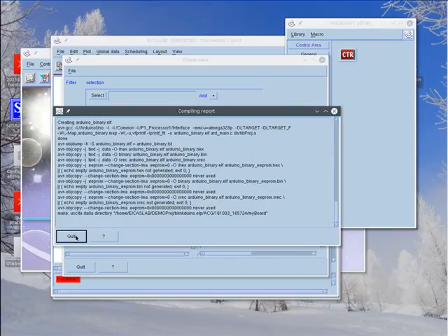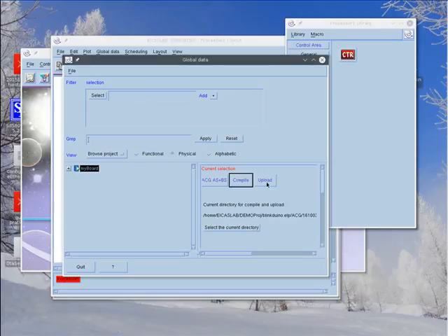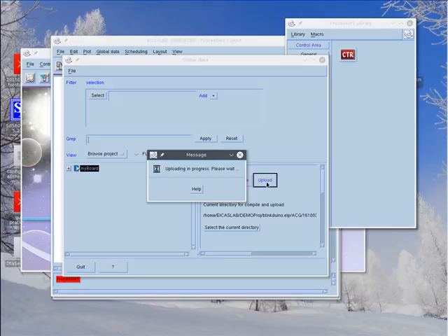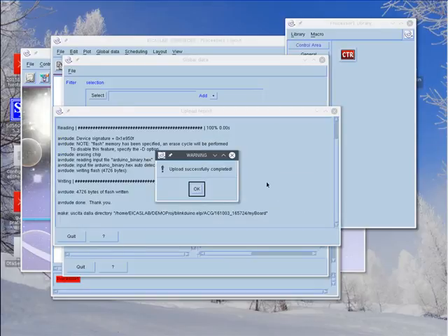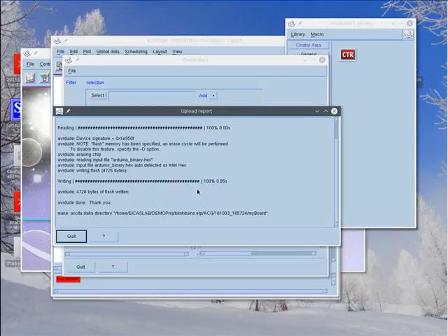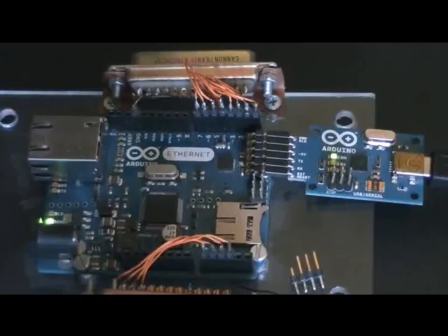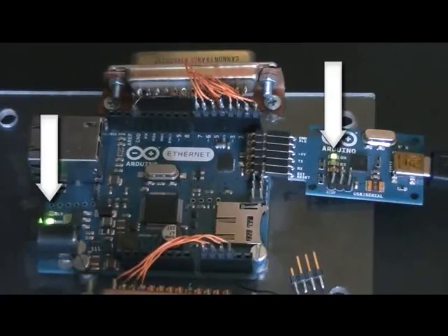The compiled output is a binary executable for the external hardware target, ready to be transferred to the flash memory of the board. For doing this, you have just to click on the Upload button, and EICASLAB will use a device programmer software for uploading the code. When the upload is completed, the board starts executing the program and then blinking with the required period.